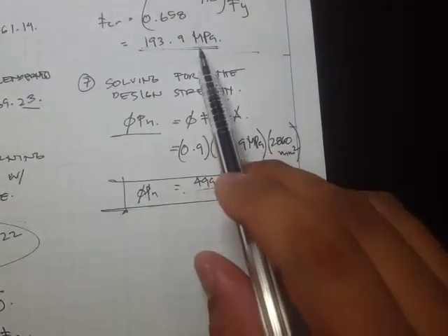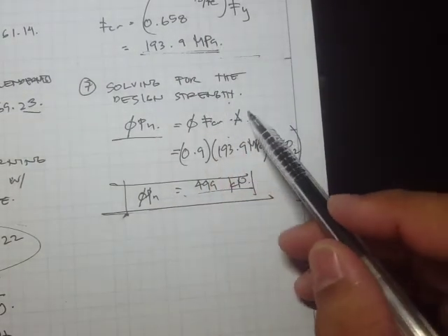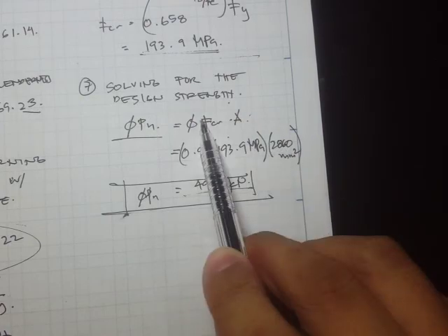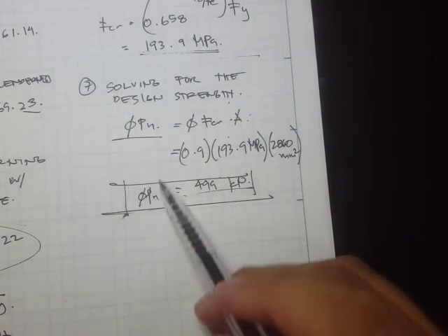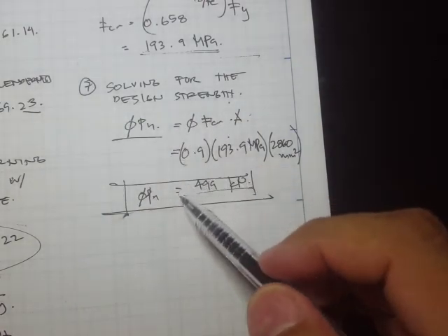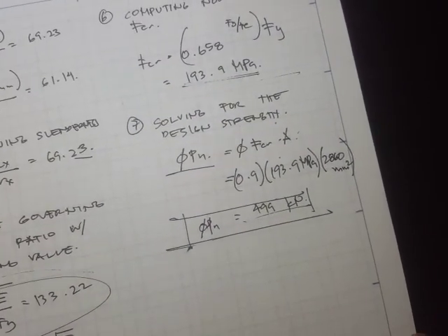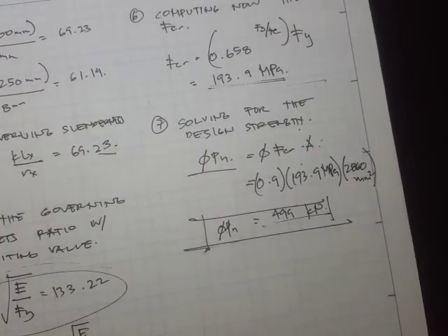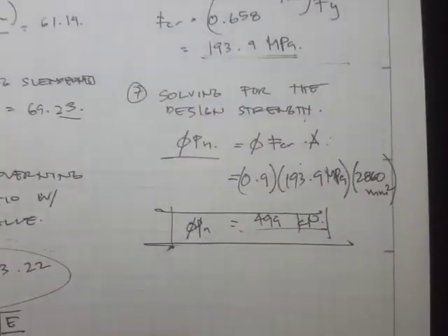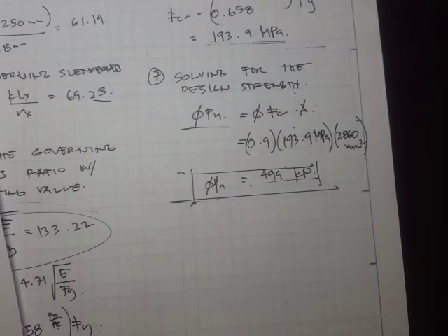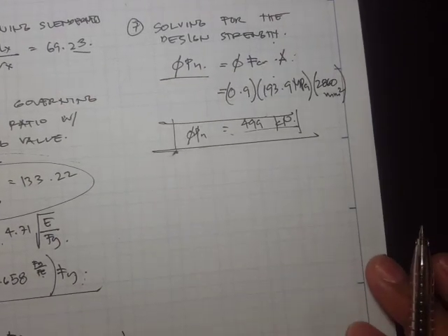And having the stress, and you already have the area, you apply the reduction factor, and you can obtain the design strength. Okay, so I guess the computations for the analysis of compression members without slender elements are pretty straightforward.